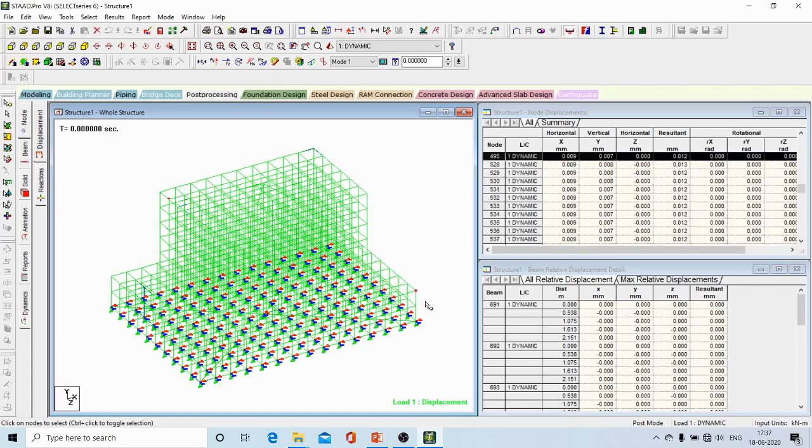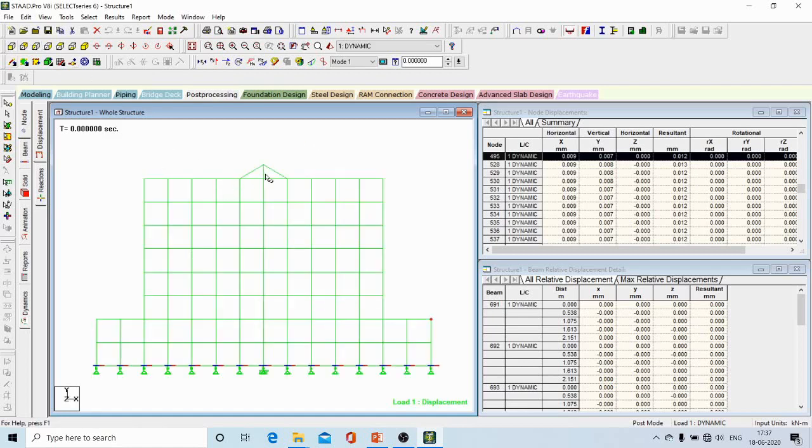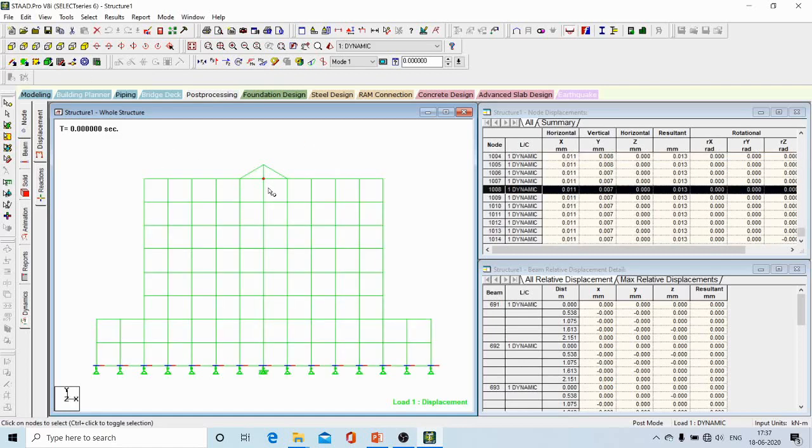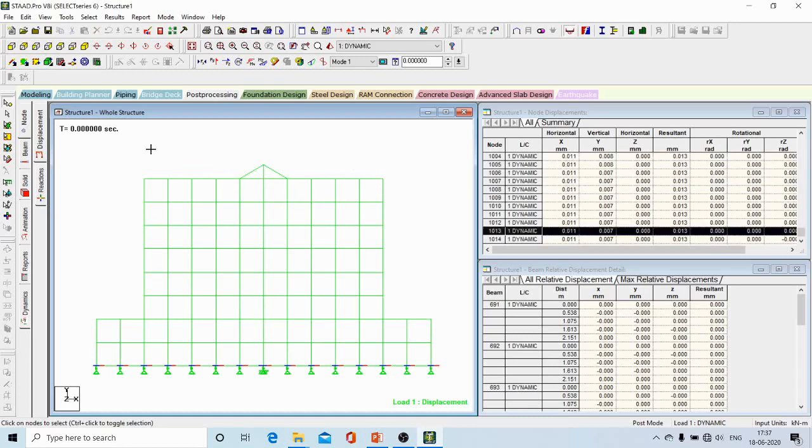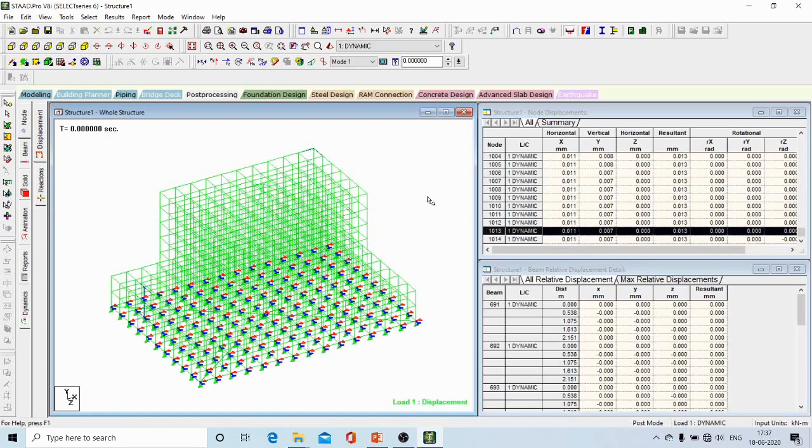Generally, in machine foundation, the amplitude needs to be checked at the point above CG at the top of the foundation, that is here. It will show 13. Also, needs to be checked at corners because the maximum vibration is at corners. In different softwares or in different versions of software, you will find some minute changes in the answers.